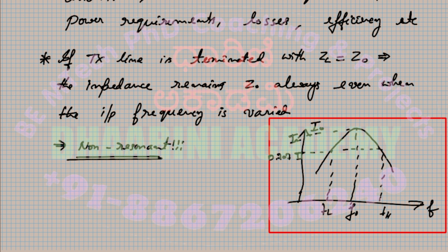So what we want is that the impedance matching device should be non-resonant. That's the ultimate point. Now you see, we achieved that. Irrespective of what frequency you give at input, no problem. It has nothing to do with the impedance. Impedance will not change, it is fixed, so that you can connect an antenna of whatever fixed resistance. No problem with the input signal. Whatever frequency you want, you send, no issue. Ultimately, that is the important thing which we wanted to achieve, and it is possible if you use the transmission line for this purpose.